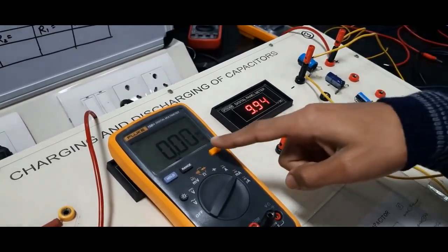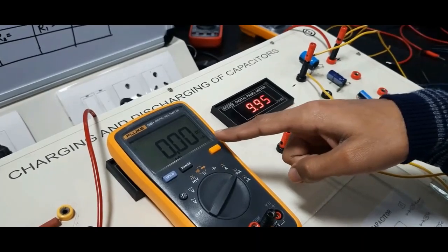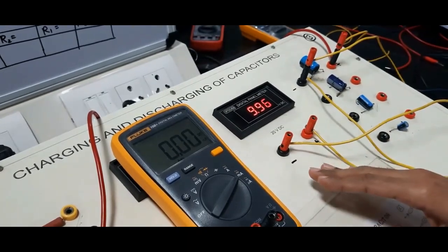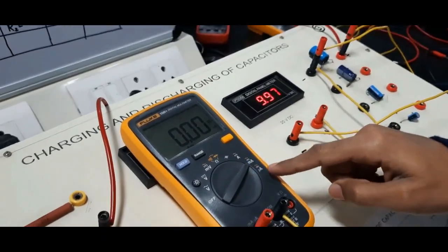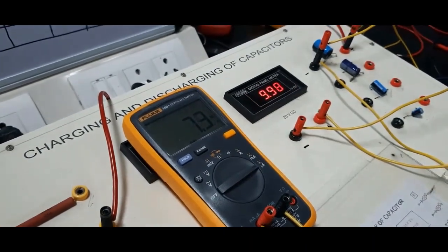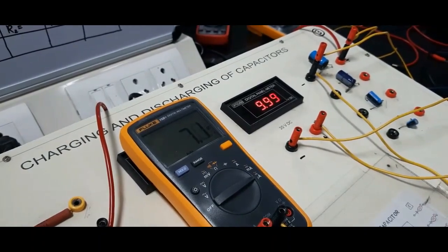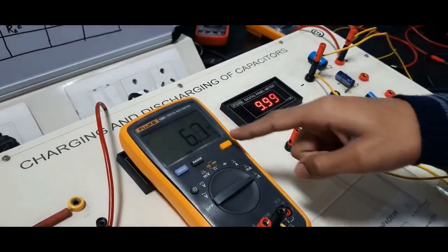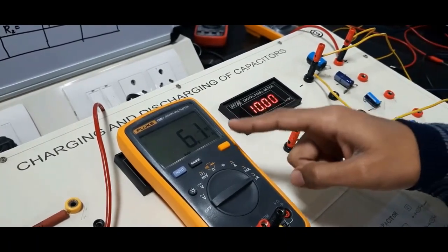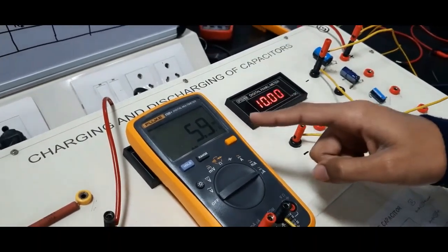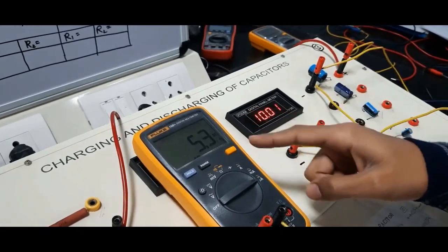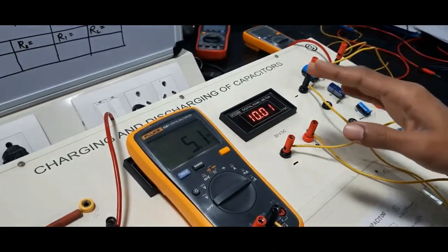So it is showing a 0 reading. The point is that we have to wait for a time which is much larger than the time constant of this particular setup. But for our time convenience, I am directly switching from the milliampere to the microampere range. So as you can see, although in the milliampere scale it was showing a 0 reading, in microampere it is showing some reading of the order of 10. So we have to wait for a time while it saturates and shows a fixed reading, and that is the reading of the leakage current for this particular setup.